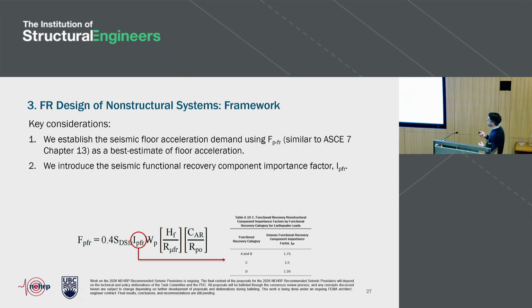We also introduce the seismic functional recovery component importance factor, which is going to vary depending on the functional recovery category. And this is essentially going to amplify the design forces in your non-structural components. It also affects drift sensitive components because it amplifies the seismic relative displacements that you need to accommodate. And by doing this, you're effectively minimizing the probability that damage in these components could lead to loss of function.